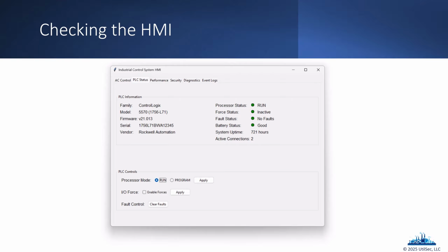And the cool thing about this is that he created this to emulate how a real Rockwell PLC would operate, in that a lot of times controllers, whether it's in run mode or not, can be controlled through things like coils. So what if I can connect to that PLC and I can flip a 1 to a 0, and all of a sudden that controller is no longer in run mode?